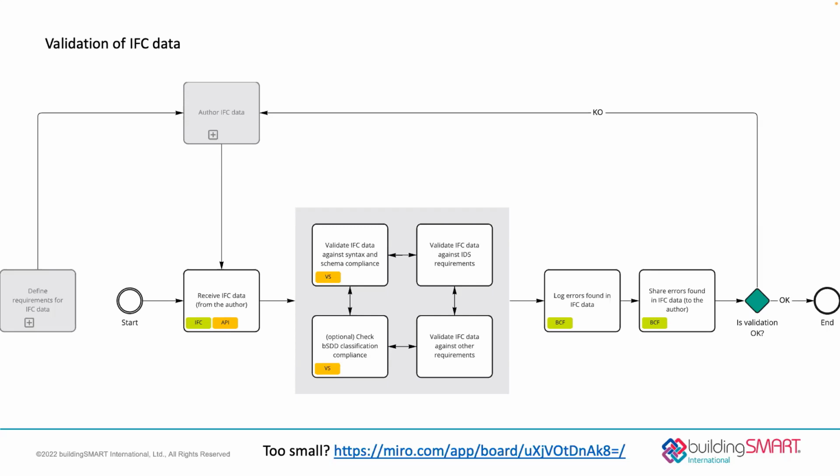And we have this BSDD check. A little bit more explanation: inside the BSDD, you can publish a standard. I know an example from the Netherlands, the NL-SfB classification standard, where NL-SfB 2122 is a load-bearing outer wall. Everyone in the Netherlands knows that. That means that an object classified as 2122 needs to have a load-bearing property set to true and an is external property set to true.